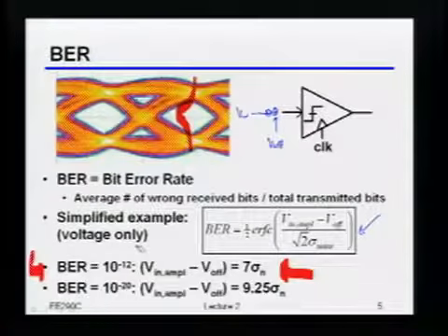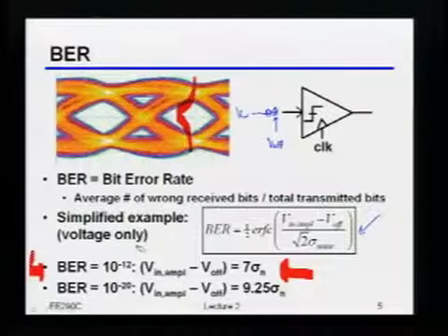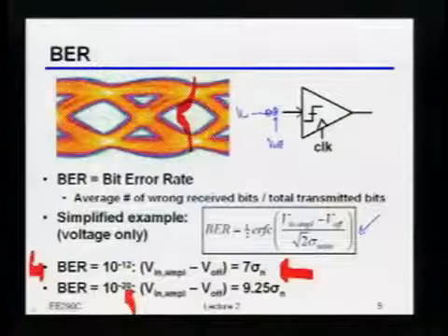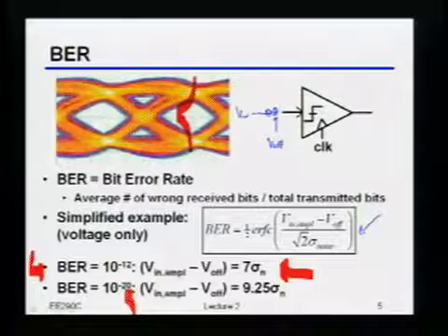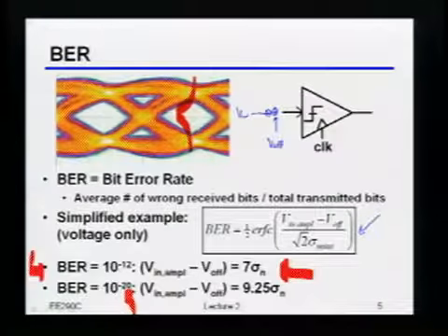Links are almost always designed in this kind of 10 to the minus 12 to 10 to the minus 20 range, okay? We'll actually talk about this some more later, but in old-time computer systems, the time they wanted between bit failures was nearly infinite. So this 10 to the minus 20 number was typically what people would shoot for in those types of systems. Yeah? How would you measure that? How do you measure 10 to the minus 20?